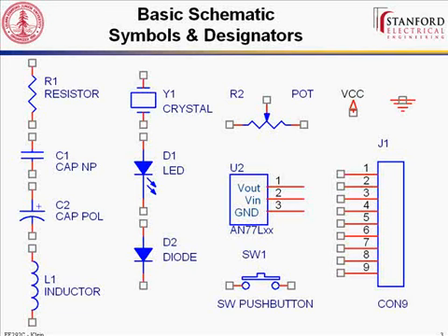So if you want to have an RLC oscillator or something like that, then you can put that in, but that's what you're actually going to translate to the board. But parts in general will translate from one schematic symbol to one part. There are some exceptions where you may have, for example, 4 op amps in a package. You'll have 4 different symbols in your schematic, but they are boiled down to one actual chip. But in general, it's roughly a 1-to-1 translation between what you see here and what goes on your board.